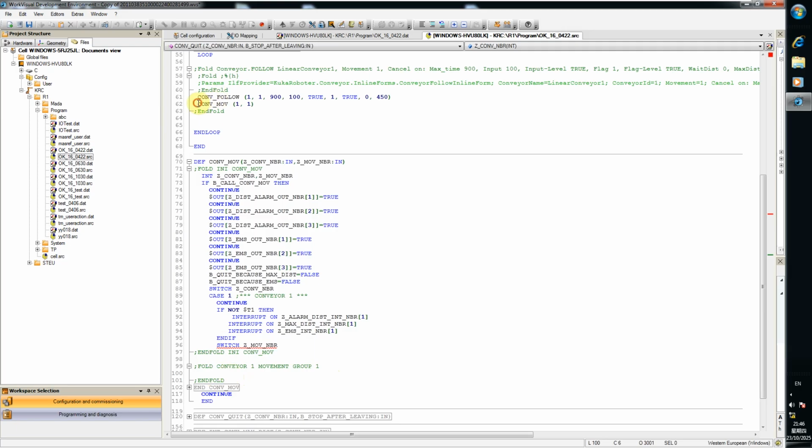So once you are under the loop, you type 1 and group 1, conveyor 1, and under this subprogram function you have to put the teaching positions. Basically, how can you teach this position? You switch the robot to T1 mode, and you run the subprogram you just established for the module.